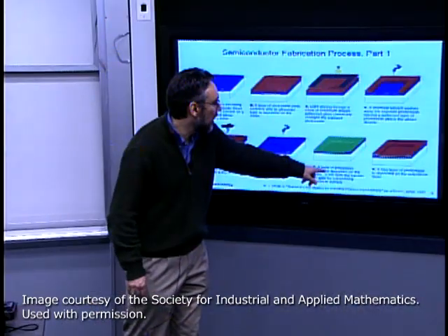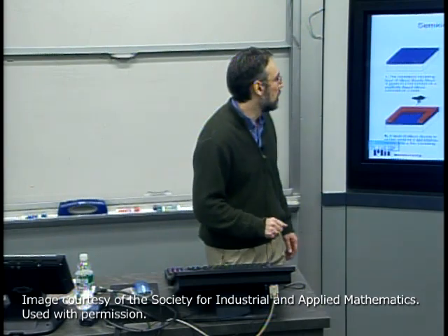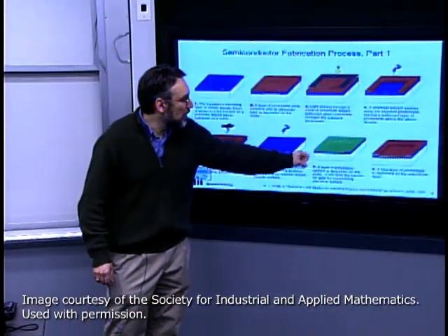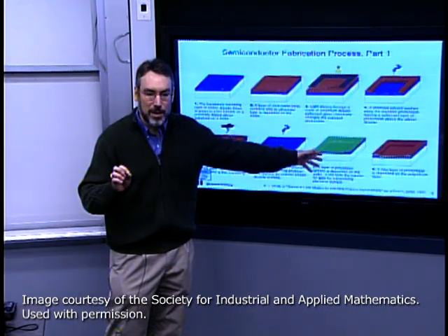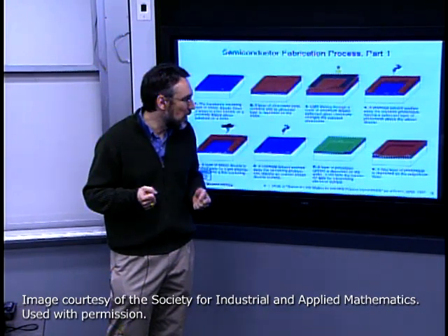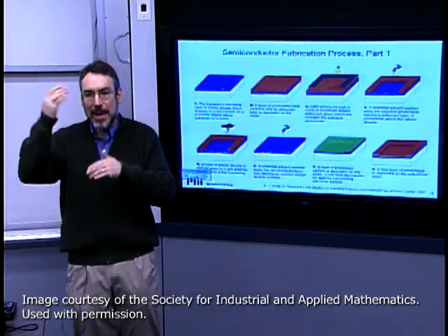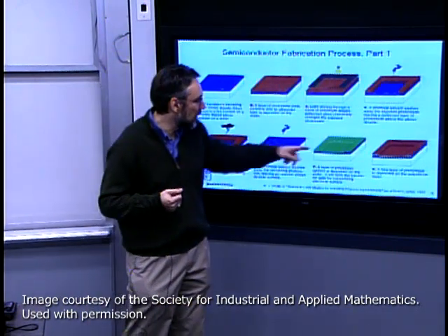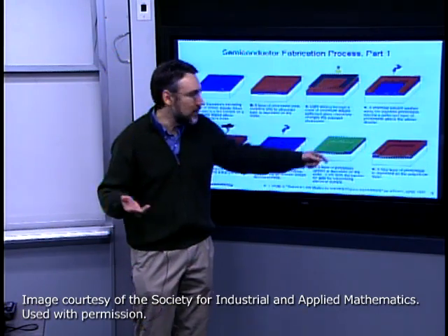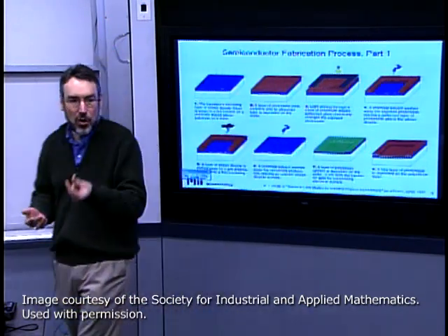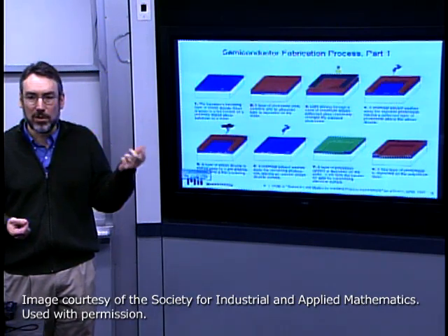And now we're going to repeat that kind of idea multiple times and then mix in a few additional transformation steps. Next step here is we're depositing our polysilicon layer. Again, this will be fairly highly doped, either subsequent to the deposition or during the deposition. It is a semiconducting layer, but if one dopes it, that is, adds elemental impurities of a particular type to play with the band structure of the silicon, one can make that behave in a fairly metallic fashion. And in the MOS transistor, that polysilicon is very highly doped and is a conductor under all conditions.